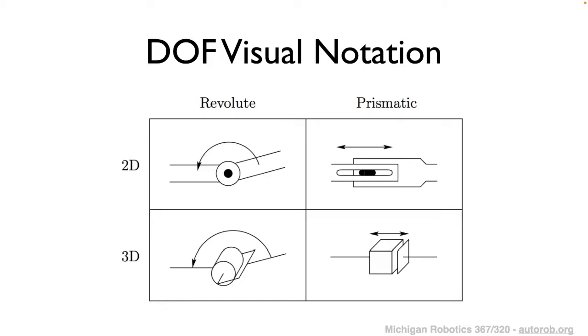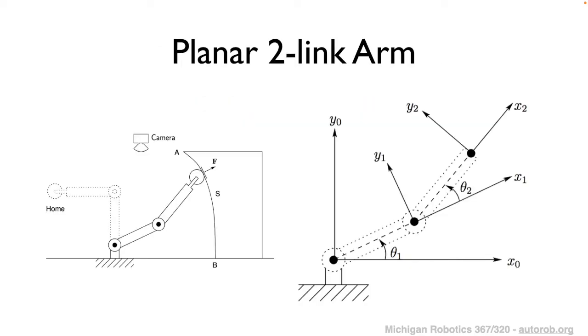And then in the second column, we have our prismatic joints, right? So once again, these are joints that connect two links, and these allow translational motion of two links with respect to one another. And so we looked in some past lectures, and as you're starting to work on your pendulum arm now, we looked at this two-link arm that has two rotational degrees of freedom, and so the two links are able to rotate about one another and also rotate about the global origin.